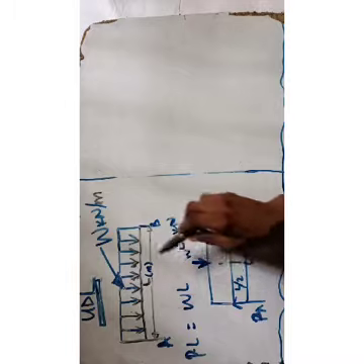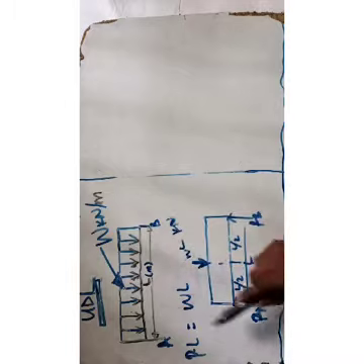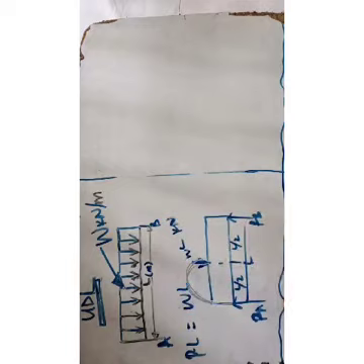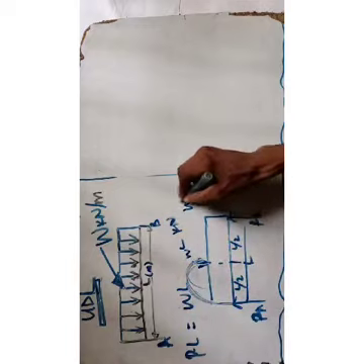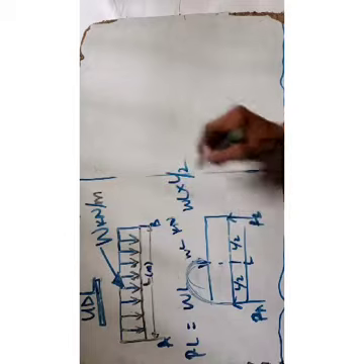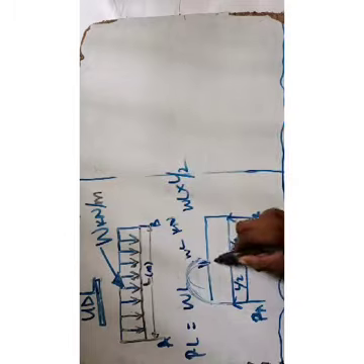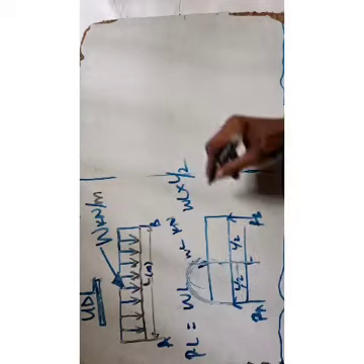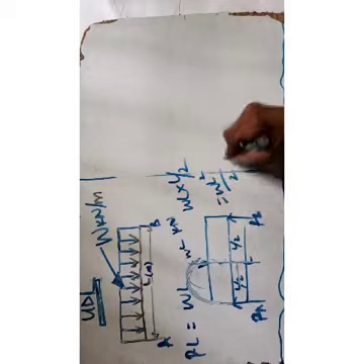Once you do the point load for this, you need to do this as well. Then you take the moment, you multiply it by the half. That will now be WL times L over 2. So you multiply by the remaining half of this, okay? Then you have it as WL square over 2.